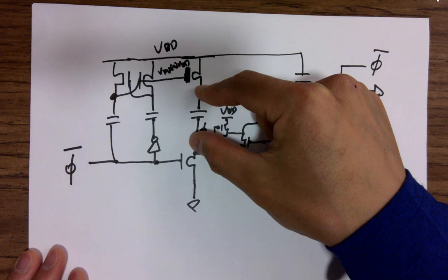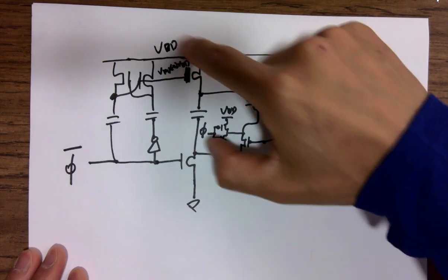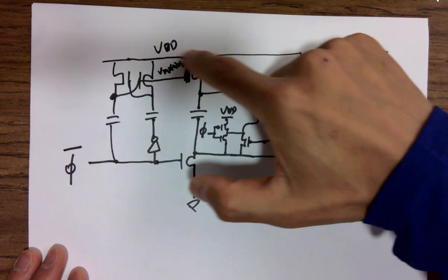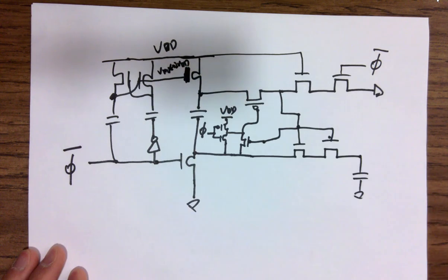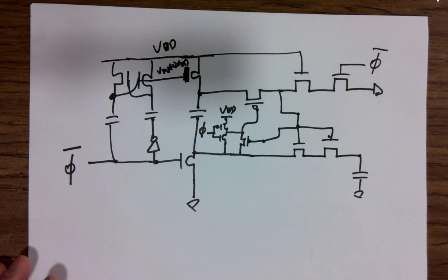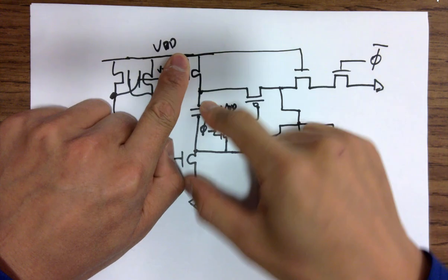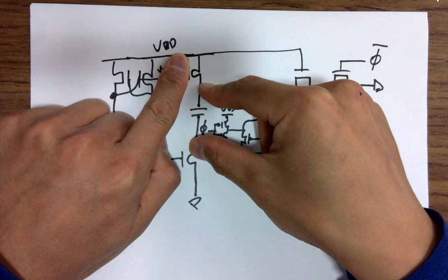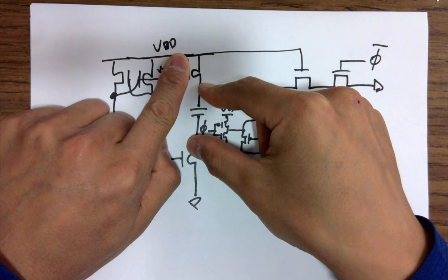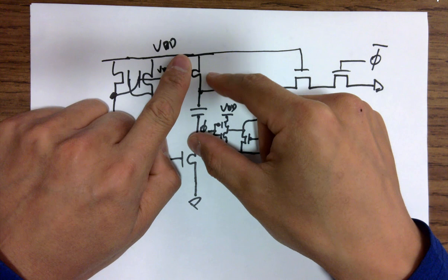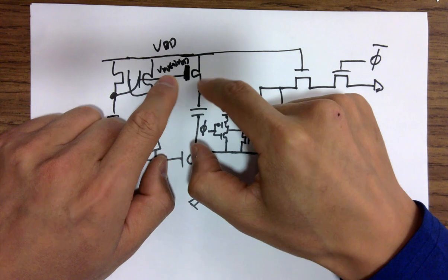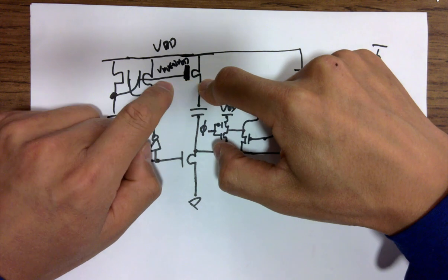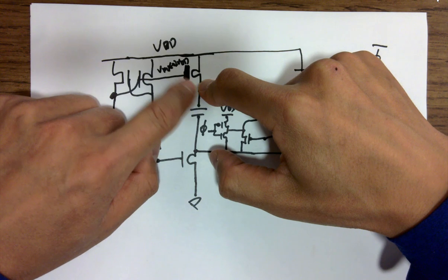So it's just 1 VDD, because on the other side, on the drain power supply, you only have 1 VDD available. So the gate is just the switch of the faucet, right? You just turn it wide open, so you are able to pass the whole VDD to the cap. Okay, it's not decreasing or subtracting the VTH from it, because whenever you are having this point charged up to VDD, what's the VGS over here?